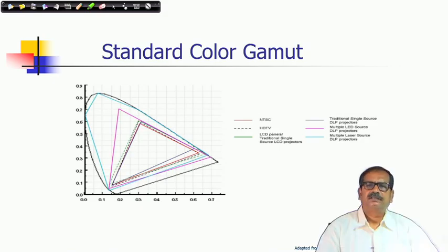There are various primaries used, which increase the scope of the color gamut for displaying colors, and in fact, there could be some kinds of display where you can have more primaries instead of just red, green and blue. That means you do not have an independent set of primaries; you can have some dependent set of colors also, whose combinations are also considered, and in that way you can increase the range of color reproducibility.